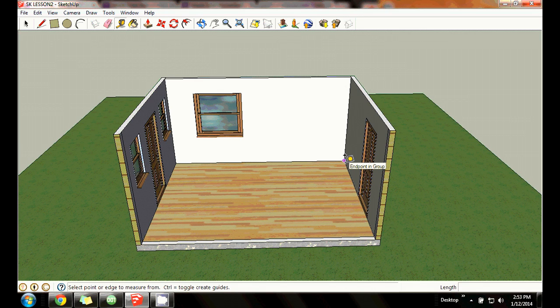Just going from the inside corner there, I'm going to measure over here, and that window is at about 9 foot. I know that the width of this house, the length of this house was 16 feet, right? So I'm going to put a wall here. Let's go over 8 foot. We'll center the interior wall. And I'm going to go over, well, no, let's go 7 foot. Okay, I'm going to make a 7 foot bathroom on the interior here. So I'm going to measure over 7 feet.